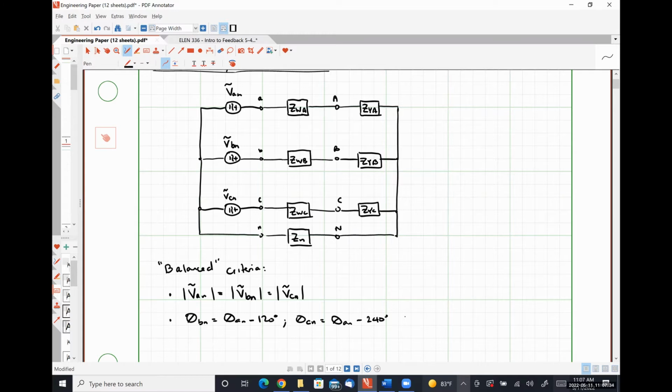What did you label that bottom left side? To the left of the N. Lowercase n? Yeah, for the neutral conductor. Yeah, so all of these voltages are measured from the transmission line terminal with respect to the neutral conductor. So for a negative phase sequence, we would have these exact same relationships, except we flip the sign on the phasing. Bradley, what's your question?